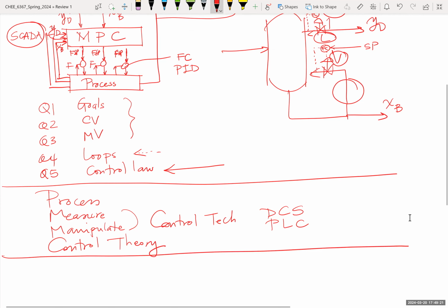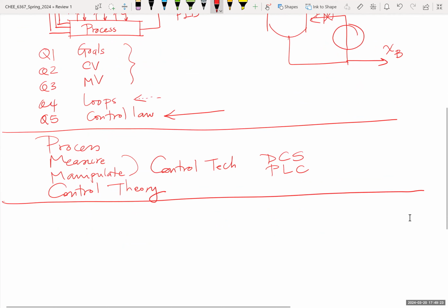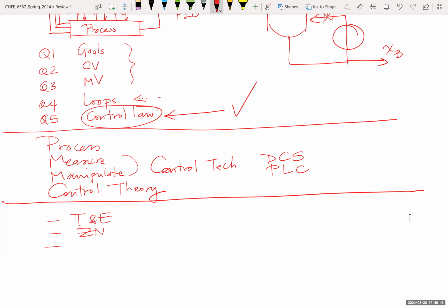With that, again, I'm saying that we spend most of our time dealing with this, again, fully understanding that all of that is important. And section 7 says, how do you design a controller? Well, to design a controller, and basically this means how do you design a control law? You can do it in a number of ways, but basically it can be trial and error. It can be Ziegler-Nichols, 1 or 2. And it can be IMC. This is good enough. You don't need much more.